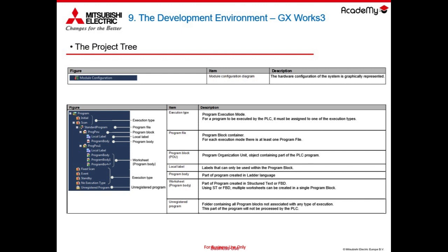What is important to say is that the program files, the program blocks, our POUs that we are going to write and design, we insert into a particular folder. As in this case, the scan folder means that we are requiring that the program file will go into scan mode execution.